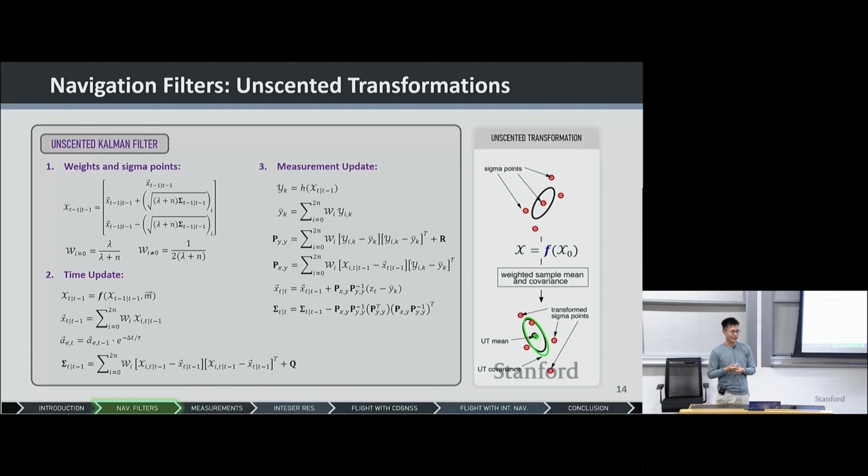Yes, we've done it for DIGITAL, our differential GNSS navigation flight software stack in the Space Rendezvous Lab. In the previous iteration of DIGITAL, it used an EKF for the time update, followed by the UKF for the measurement update. The reason is that the UKF is generally better at capturing non-linearities in your processes.